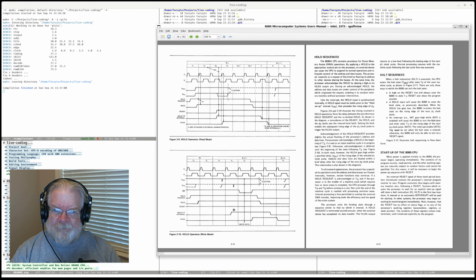M2T1, when we decode the MVI, we're going to have to select the M2T1 for bringing in the second byte of the instruction. And also, we need somebody to set up the 3. And I think during this T1, T2 time is when we can reach out and say, well, we're going to need M2, T3 real soon, so let's use the opcode in IR to select that. So we're going to defer setting M2, T3 until we get into this. Okay, that's how it shakes out.